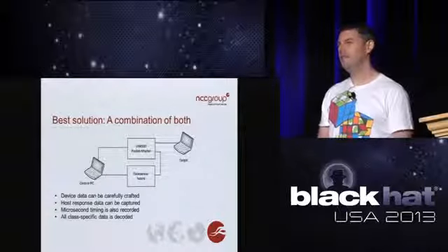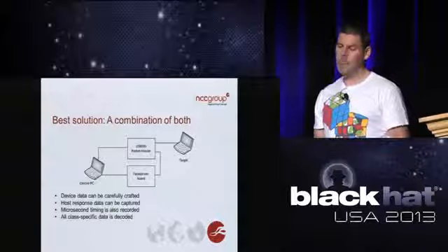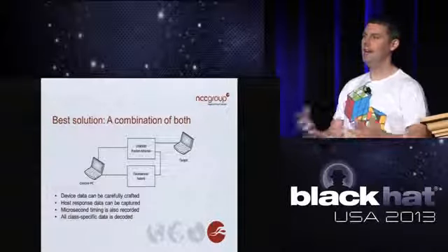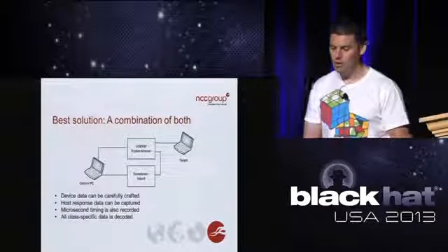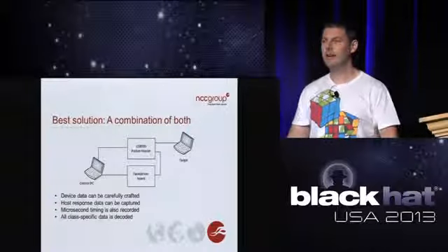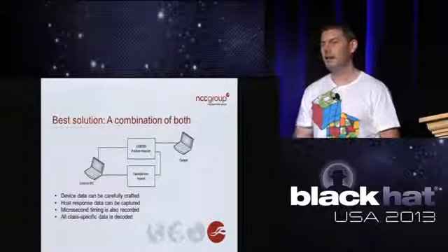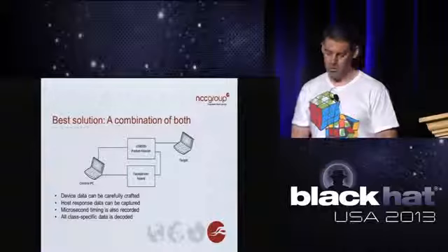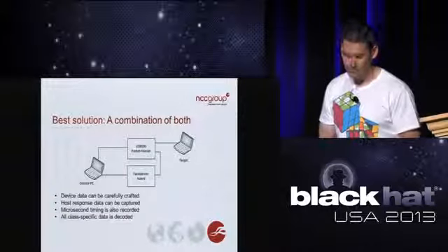So to use a Facedancer to actually generate the traffic, but then because you're looking in detail at the traffic that's coming back, you need to be able to capture, decode the classes, and interpret the data using the commercial USB sniffer.